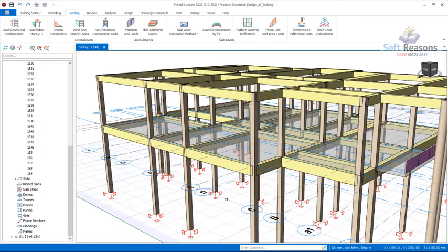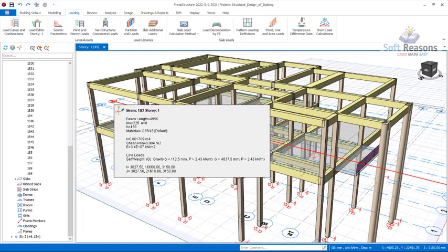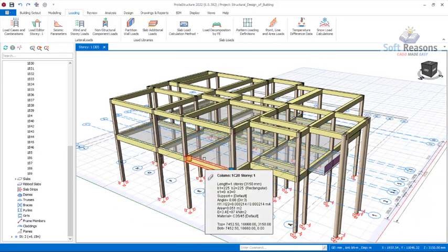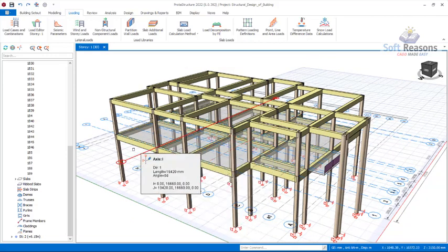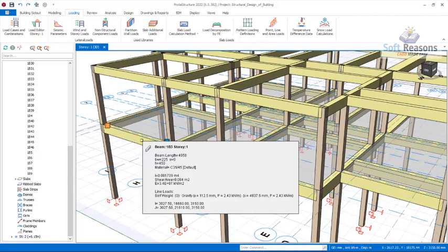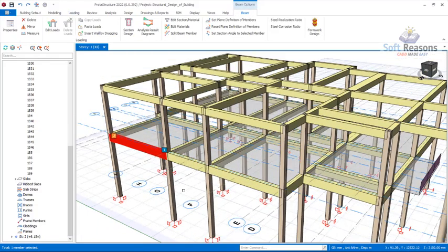Okay, so the blocks are 9 inches block. Alright, so for 9 inches block we have about 2.4 something kilonewton. But once you now add some additional loading for finishing, you have about 3.47 kilonewton according to laboratory test. All right, so this load is directly on the beams, okay, from the beams to the columns and to the foundations right there.